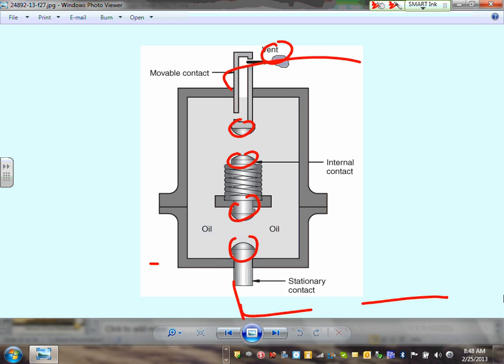When you have a short circuit condition, guys, I always describe it as, imagine you have a semi-trailer running in front of you at 85 miles an hour, and you're behind it, and that semi came to a complete halt, and you are running at 85 right behind it. What happened to you? Right, slam into the semi. That's the amount of energy that you interrupt when you have say 600 amp at 15 kV or 13.8 kV, and you're trying to interrupt it. That's the incident. Everybody understand that, guys? Yes, no? Okay, so that's another way to interrupt from two locations.